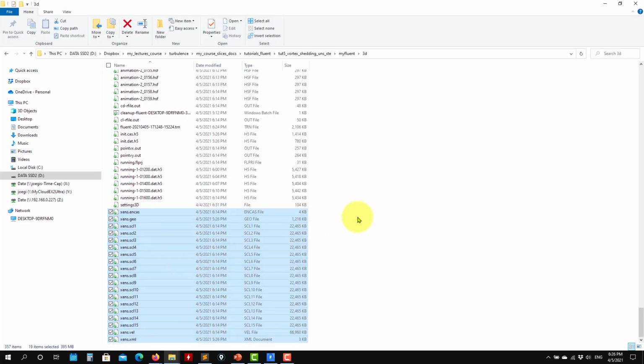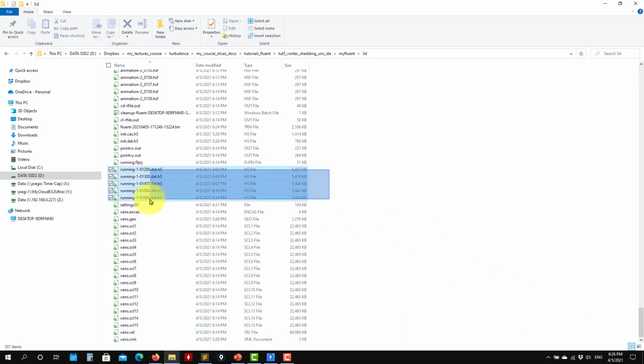So here you have all the information saved with a given saving frequency, so you can do nicer animations here, and you access all the data that you saved there. Then see that you will save the last 5 files in Fluent. So if you want to restart from here, just open it with the case and you are done. Here you have the text file.